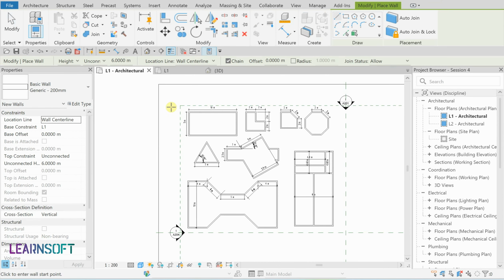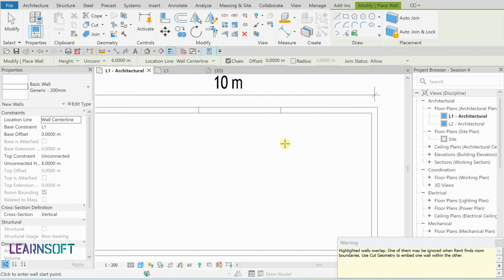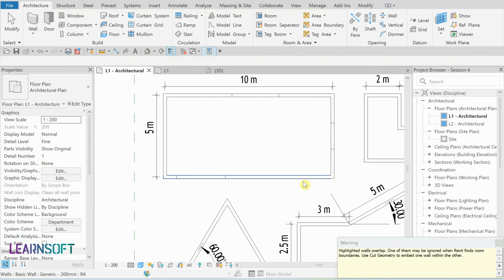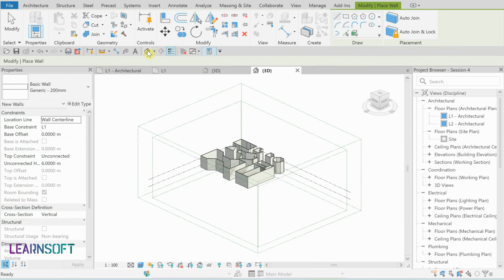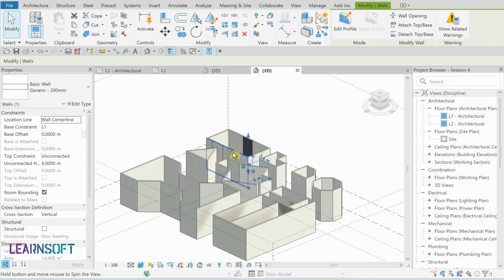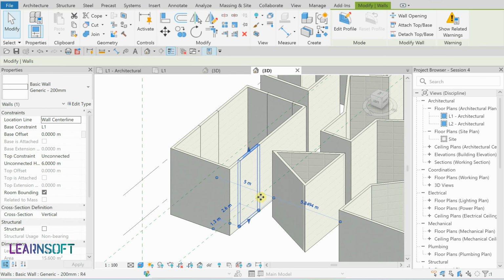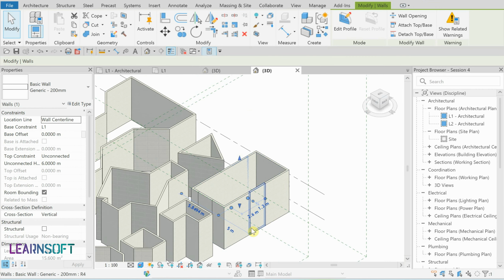Another skill that any BIM expert needs to know is having full control of elements in the project. Avoid overlapping, interference, and clash between elements. The 3D model shows that there is wall overlapping and it should be solved. For precise and efficient building information modeling, we need to pay attention to details. Modify or selection tools allow us to select and remove them.